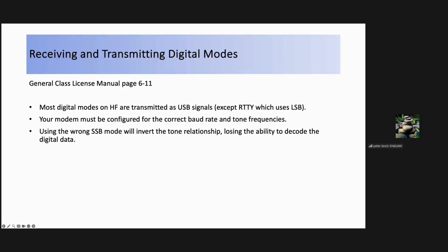All right, receiving and transmitting digital modes. Most digital modes on HF are transmitting as upper sideband signals, except RTTY, which has traditionally used lower sideband. Your modem must be configured for the correct baud rate and tone frequencies. And we've talked about baud rate at different sections of this class.